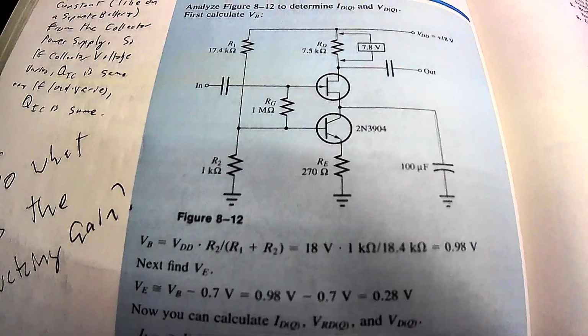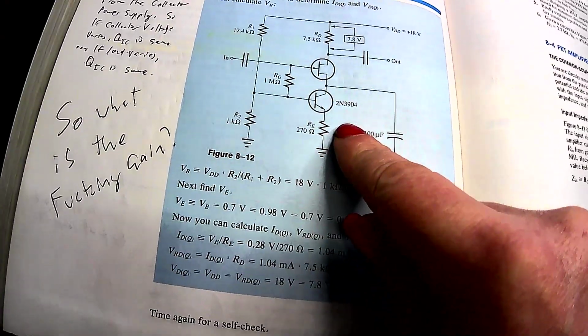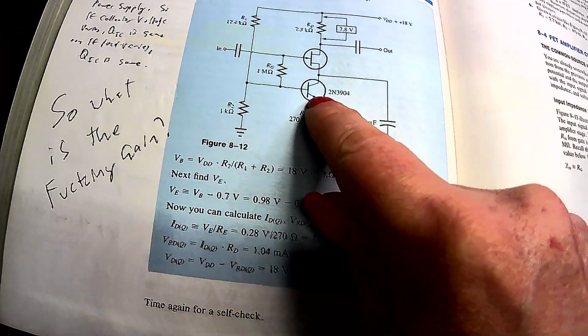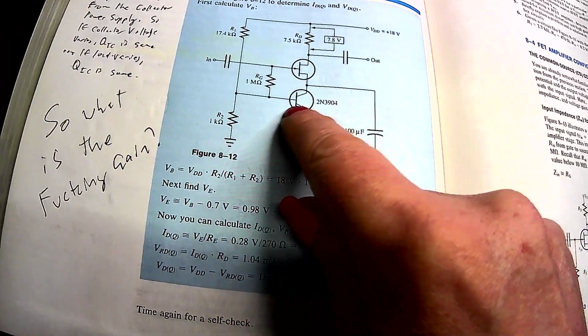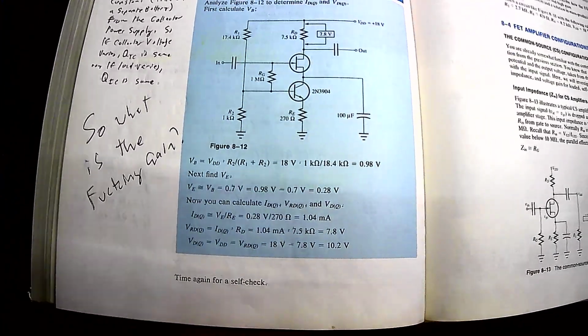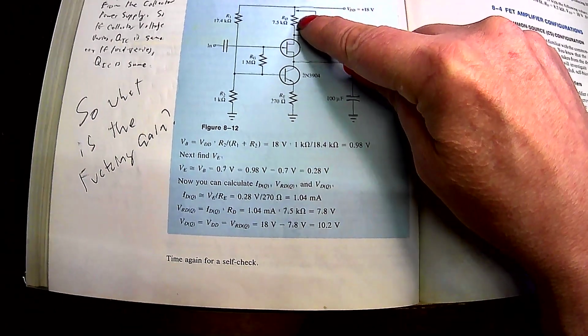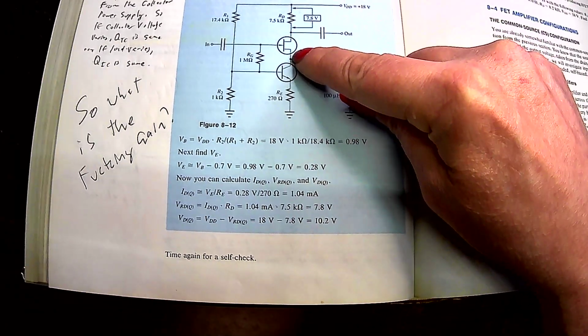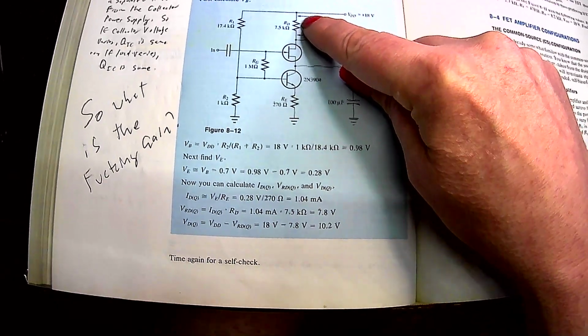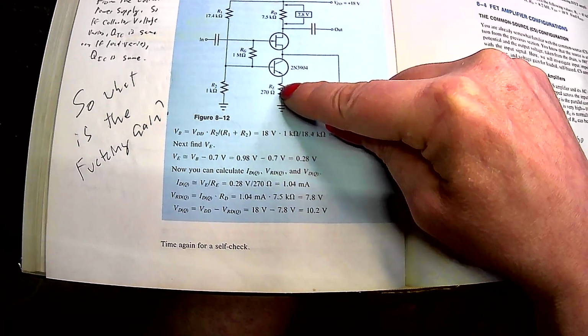One last thing on the JFETs issue. There are circuits like these, that are based on setting up a constant current source with a bipolar transistor, and that's supposed to minimize the parameter spread, because it ensures a constant current through that, and therefore a constant voltage drop across it. And a baseline for the current.